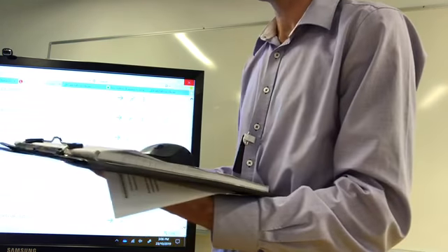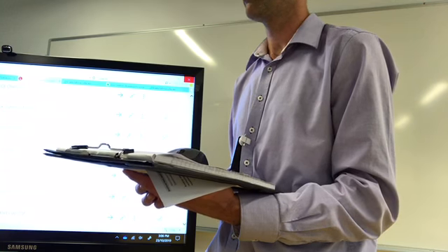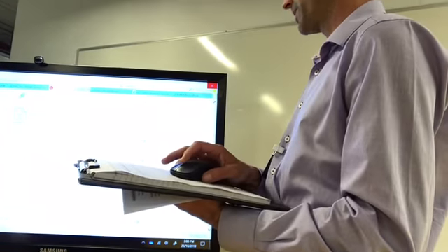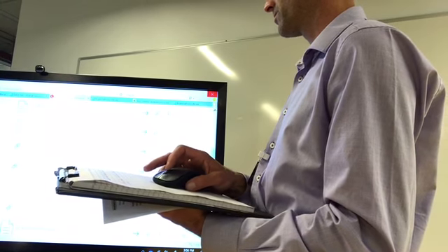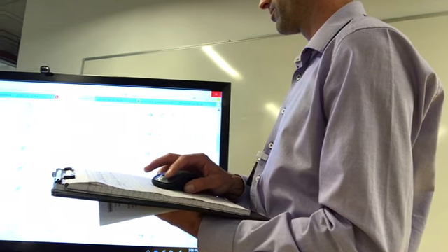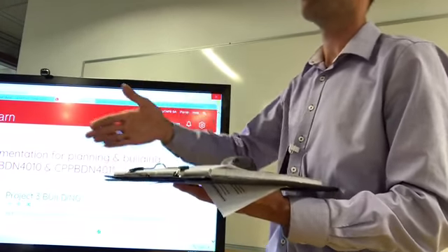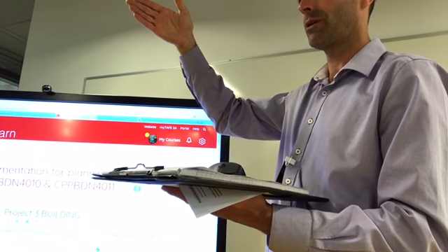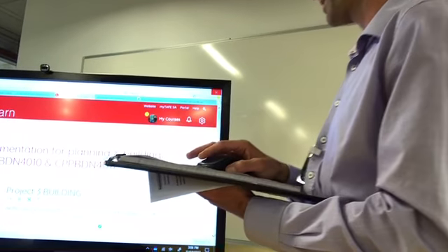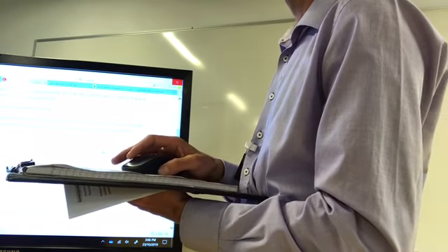So if you're going with your flat concrete roof, I guess we've covered it fairly well. What I don't have ready here is a detail for the EPDM membrane going up your formed parapet, and then a flashing coming over the top of that.